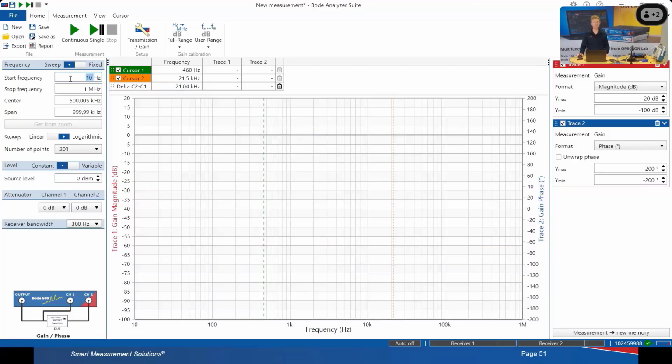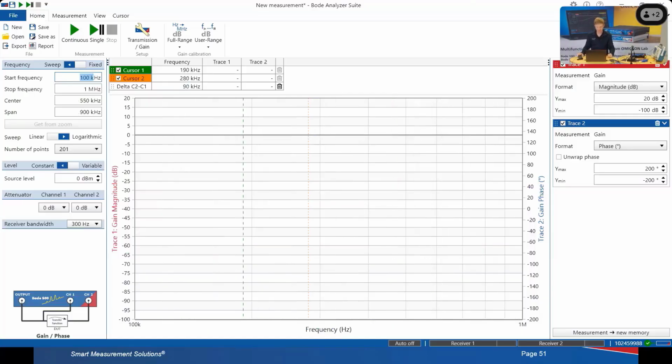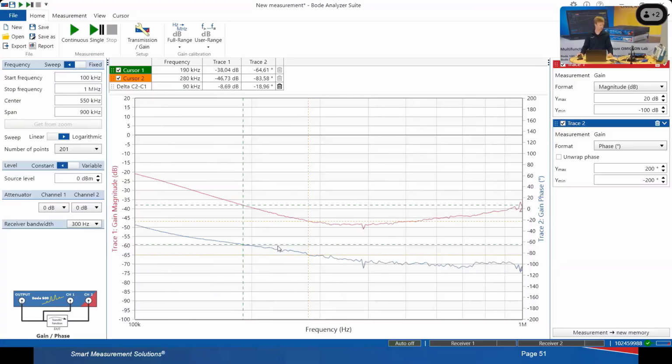And the first thing that we do is select the frequency range. In that situation, it's a quite fast control loop, so let's go from 100 kilohertz to 1 megahertz. The switching frequency is at 700 kilohertz, so I don't go higher. And well, I think that's basically it. So let's press the single sweep button, and something doesn't work, of course. That's the effect of a demo.